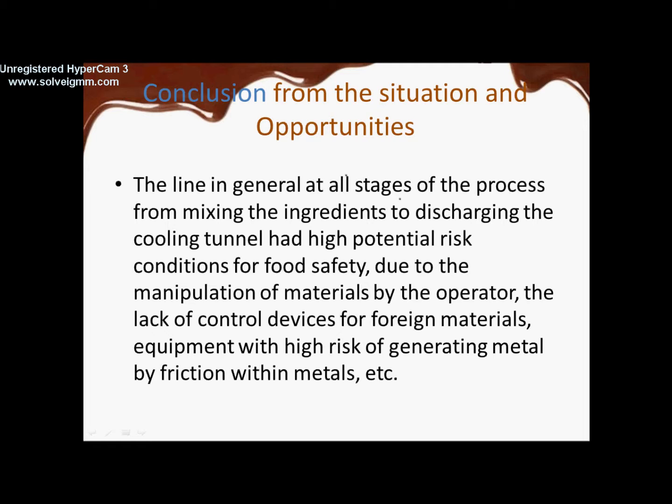Due to the manipulation of materials by the operator, no control, the lack of control devices for foreign materials, equipment with high risk of generating metals by friction within metals. Like I said before, at the end we had a guillotine, which was metal, and the band was metallic, so even though at the end there was a metal detector, sometimes it doesn't detect everything.